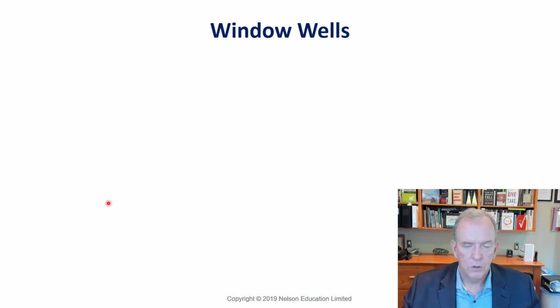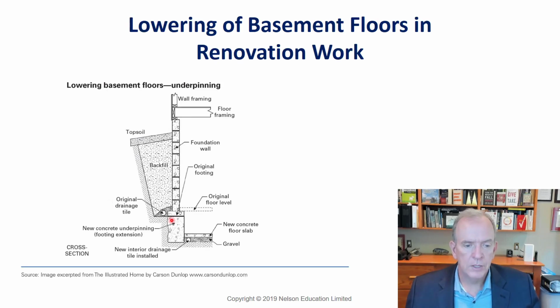So that's giving you an idea of lowering a basement. I should mention there is another methodology, which is benching. Benching is you don't dig underneath the existing footing. You actually build out a bench. So if you want to go down 2 feet, or let's say you want to go down 10 inches, all right? 10 inches, then you have to come out with the bench, usually more than 10 inches.